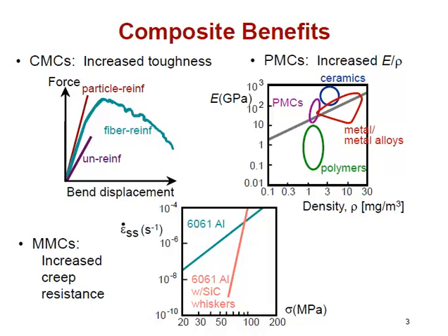That represents the point at which we've exceeded the capacity of that ceramic matrix and started to crack it. And so we've started to lose cohesion between the reinforcement and the matrix, but we still have enough to carry the load and transfer it. And you begin to see now the fiber carrying all of the load until it starts to fail.